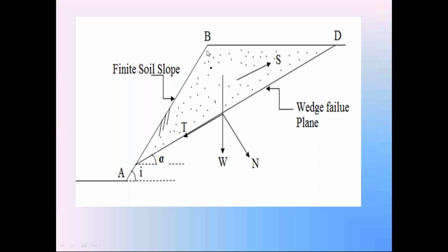In future, after construction, if the failure happens in the worst conditions, we know that this finite side slope is subjected to failure because of a number of forces: because of the gravitational force, because of the seepage flow of water, because of sudden drawdown in the water level, because of erosion, because of earthquakes. This side slope may be subjected to failure in the future.